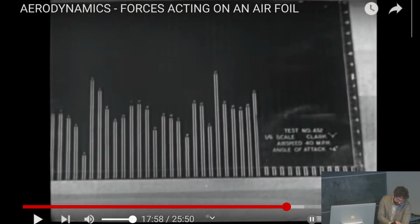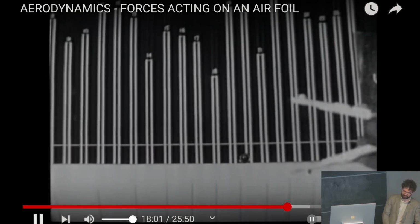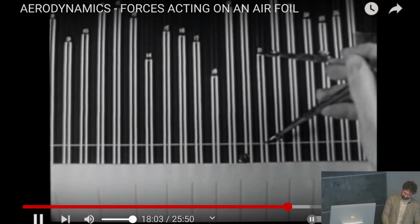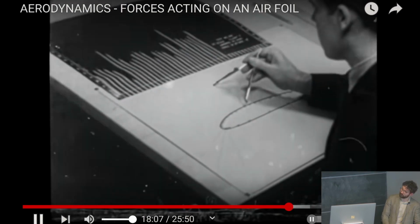So they take a picture. This is, by the way, how a lot of the airfoils used on modern planes were designed and originally tested. They take a picture of this bank of manometers, and then they measure the height in the photograph to assure simultaneous readings of all tubes, and the photograph is used by engineers to plot the pressure curve.